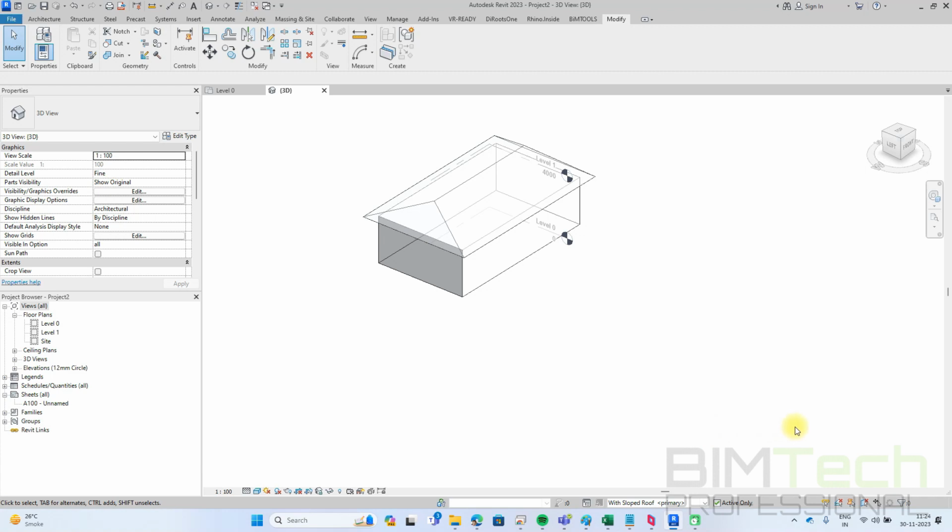This is how the design options work. It can work with all the other elements in Revit. Okay. So in case of the LOD 300 model, wherein you add the walls, you add the finishes, and you want to show different finishes options, you can do it with the same kind of command. So you add those elements to a particular set and then toggle the set from this particular option, this particular feature. All right.